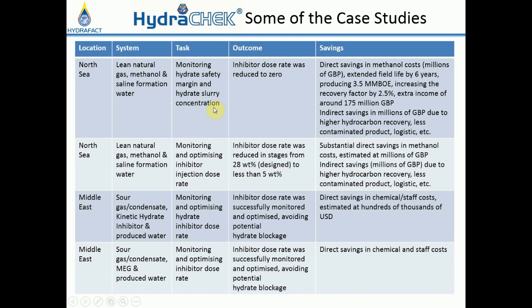For example, if the background water salt concentration is 4.5%, and 10% of water is converting to hydrate, because hydrate excludes salt, the concentration of salt in the remaining water increases by 10%, which will become around 5%. So if the concentration of salt goes above 5%, it means that more than 10% water is converting to hydrate, and then the operator needs to do something about that.